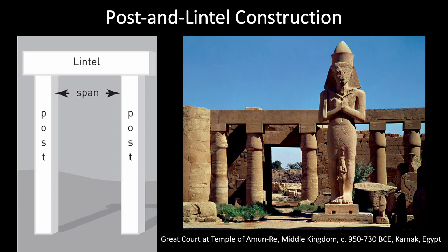While stacking and piling can produce monumental structures that can withstand the test of time, it really only provides small, dark interior spaces, if any at all. To create an interior space, an architect needs to create a span or a distance between two supports within a structure. One of the most basic, ancient, and effective ways of doing this is through post and lintel construction, which consists of a horizontal beam or lintel supported by an upright post at each end.